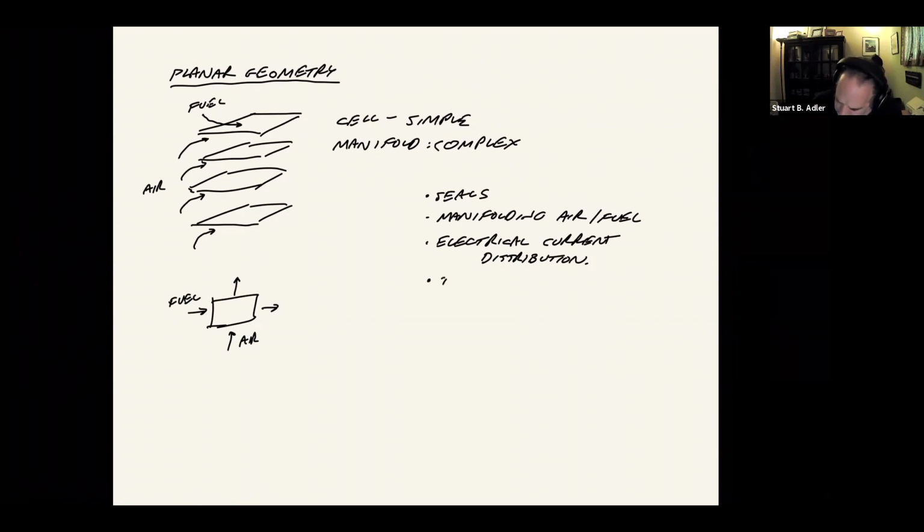Another issue is thermal or chemical expansion. In SOFCs, it's mostly thermal expansion and contraction as this thing gets hot or cold. PEMs expand and contract a lot with humidity. So as you put water into them, the polymers can expand. It can cause them to buckle and dimple. So we have to be careful about how this whole thing is put together so that when it becomes humidified, we're keeping everything flat.